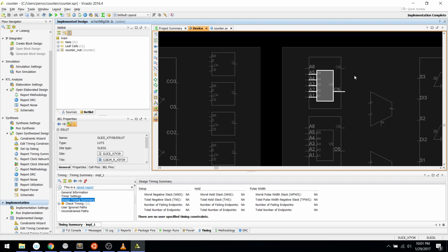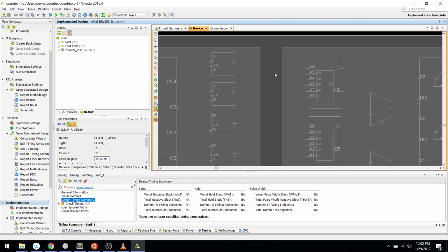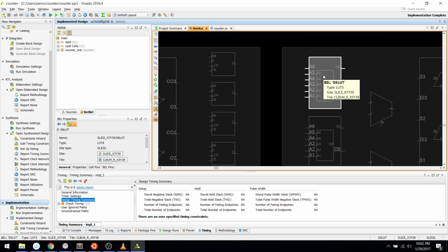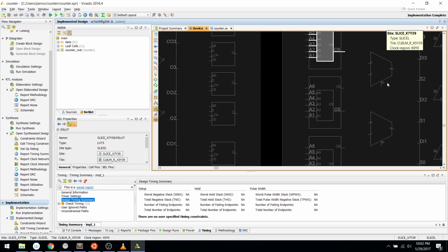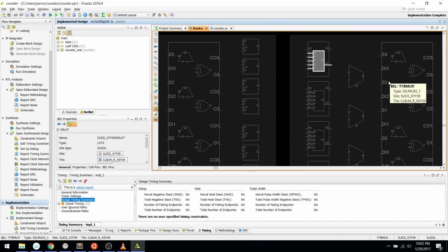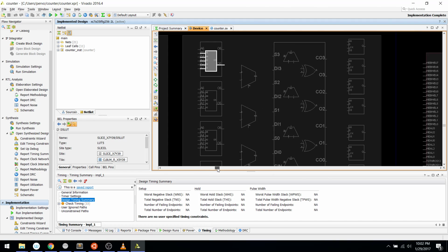The lookup table is essentially programmed at startup or at reconfiguration time, which is not something you do dynamically typically, but it is possible to do some things dynamically. But essentially, you should think of these as almost like EPROMs that are hard-coded at config time. And then after that point, they can do these operations really quick where you feed the inputs and it generates the corresponding output. They can represent any possible function with 6-bit inputs and 1-bit output, or 5-bit inputs and 2-bit outputs.